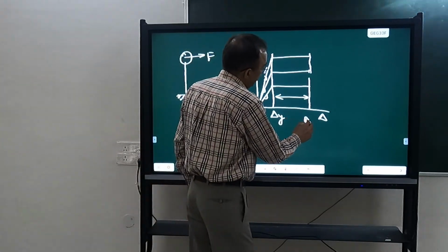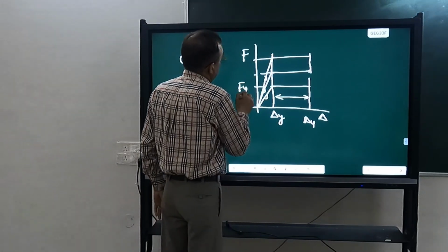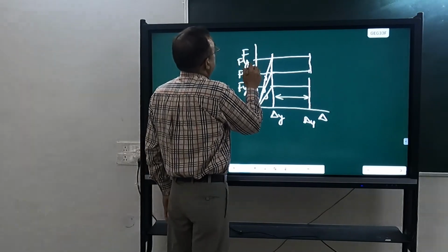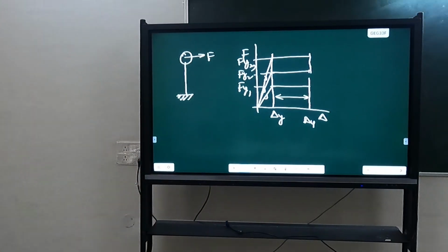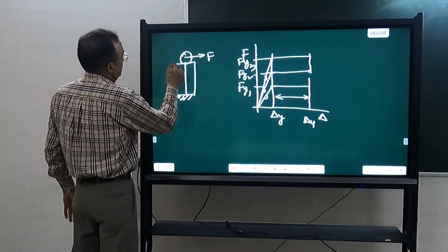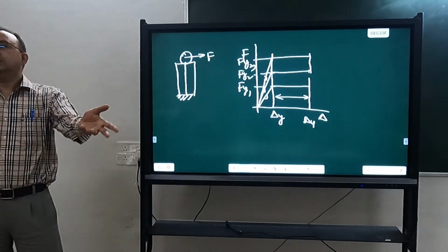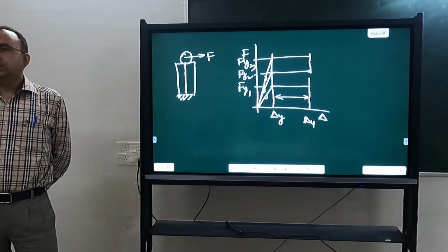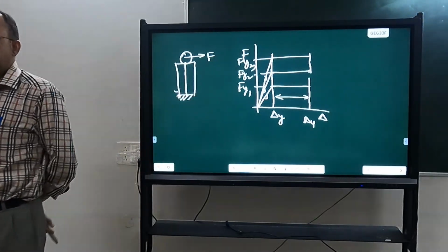Delta u also does not change, but Fy can change. You can change Fy. How? By putting a larger column size. In one case it is this, in another case you take this size and put more reinforcement into it. So you can go on changing its Fy, the force at which it is yielding. When you are changing the size and the reinforcement, actually stiffness is also changing.